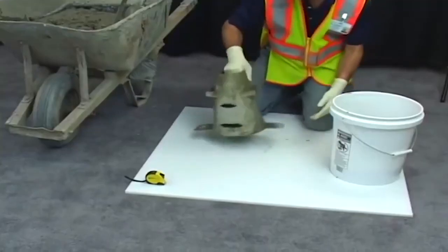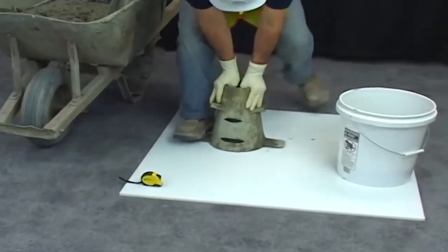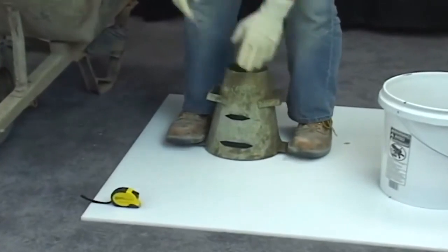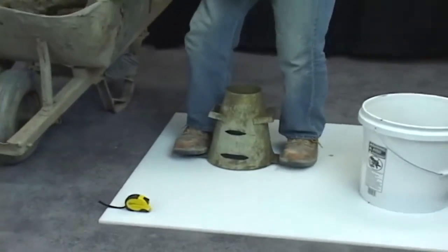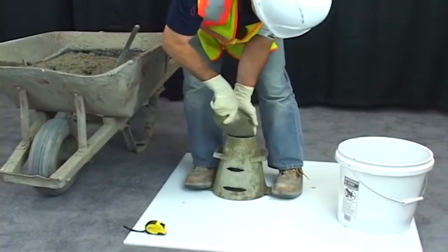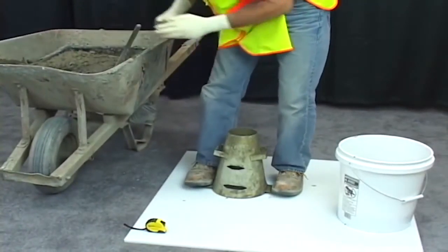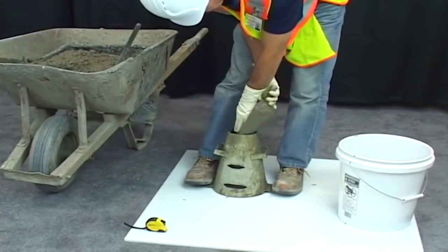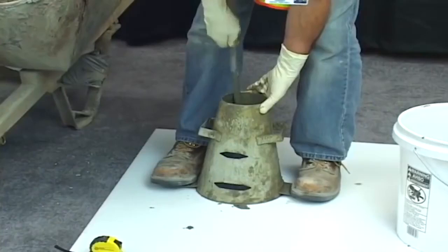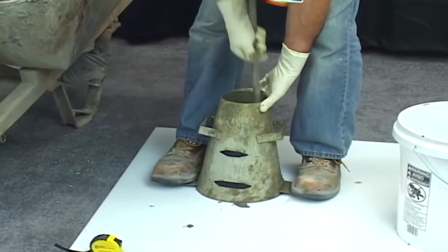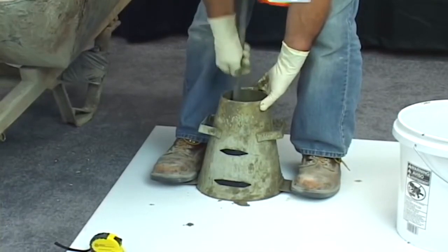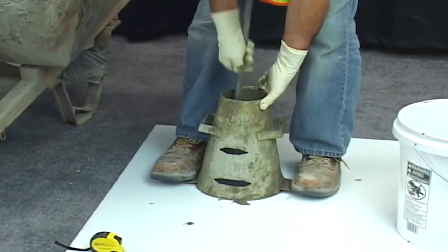Concrete, which is used for pile concreting, must be tested for its strength. Before the concrete is poured into the pile, a sample of concrete should be taken to the wheelbarrow. Then the slump test is performed. Normally, the slump and the flow values should be high in the concrete used for pile concreting. The typical value for the slump is between 180 to 220 millimeters.